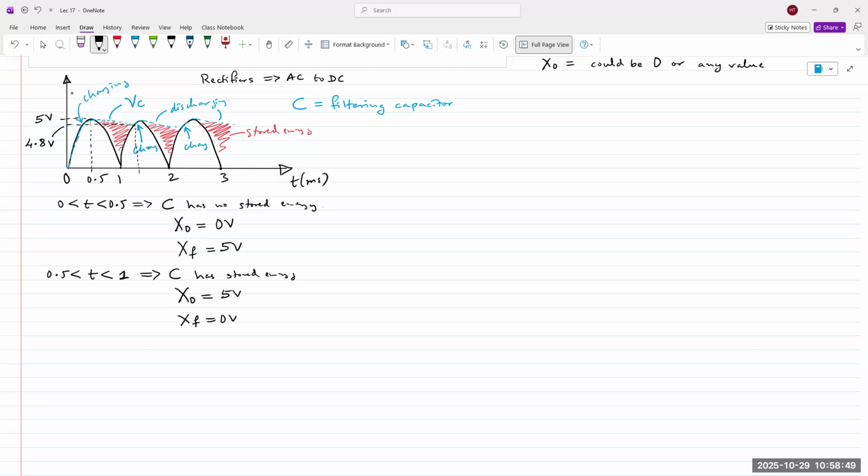Does everybody see what I'm saying? The capacitor is discharging, and eventually sometime in the future, it's going to reach 0 volts. So if I'm trying to describe an equation for the discharging portion, the final value is always 0 volts. This will be interrupted right around here. I don't know what the time would be. It wouldn't be 1.5, it would be less than 1.5.